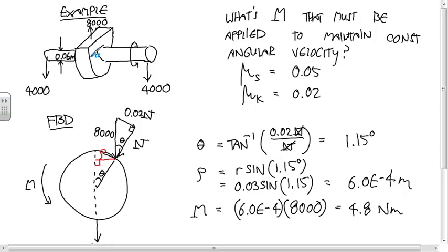So on your last page, you told us that the moment was the weight times the moment arm rho, which doesn't depend on theta. You don't even need to do all that. To get rho, you have to know the angle. Yeah, you're doing all of that to get an angle just so you can calculate that moment arm.